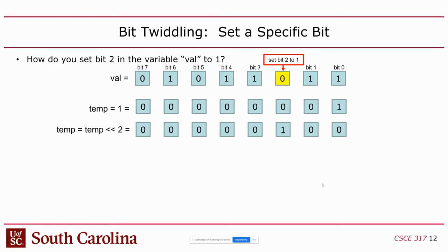Now you might be saying, this is already starting to sound a lot more complicated than it should be to set 1 bit, but it turns out there's no other way to do this. In C, you can't. C doesn't have any native support for setting individual bits. Well, I shouldn't say that, because you could create a bit slice structure, but arguably that's probably just as much work.